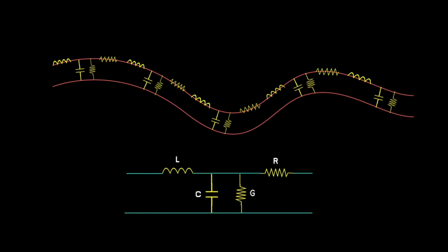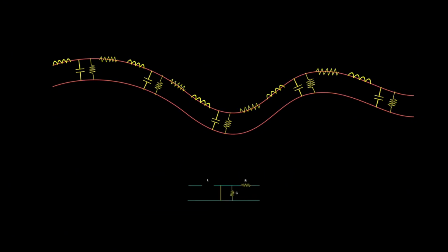This is known as the lumped element model. Using the lumped element model here gives us a completely wrong answer. Even at very low frequencies, the large series inductance would act as an open circuit, whereas the large shunt capacitance would make the wire a short circuit.